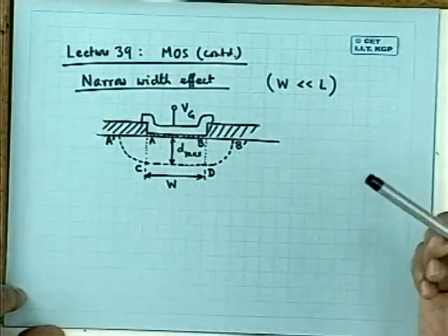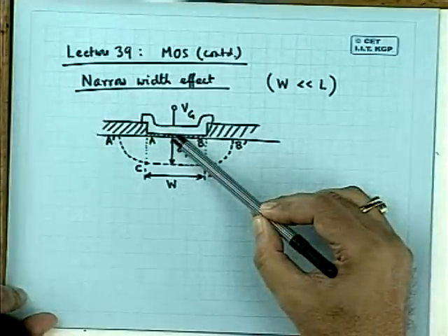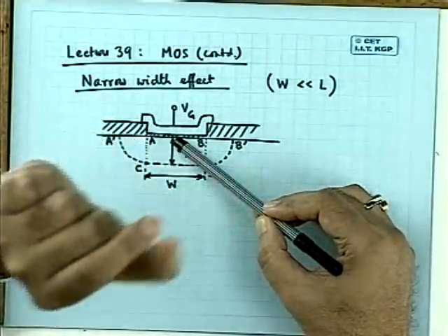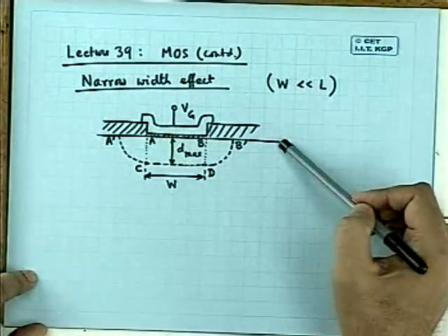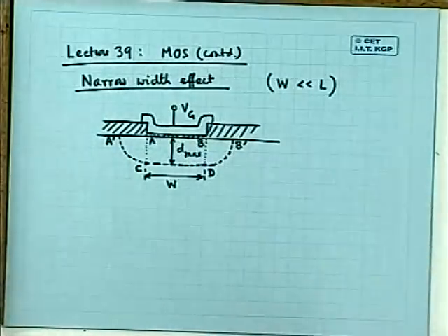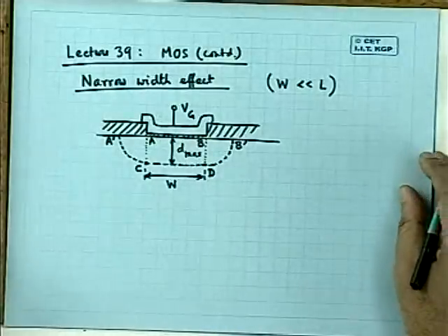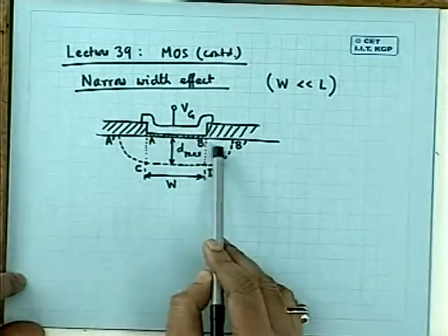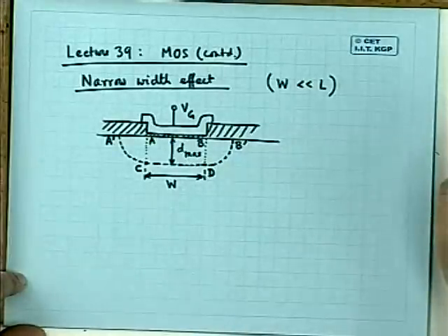Normally it is a required thing that the actual threshold voltage should be the proper value desired, and the field threshold voltage should be very, very large, and there is some thumb rule. I'm not going for that. And for that, what they normally do is an implant over the rest region called field implantation.